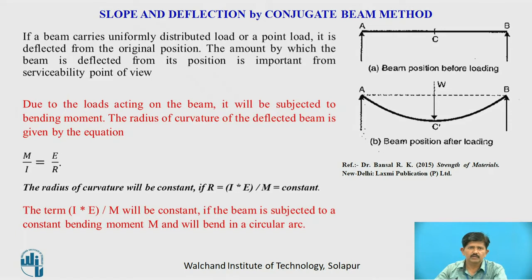So, there is much more importance to calculate the slope and deflection of the beam. If a beam carries a uniformly distributed load or a point load, it is deflected from the original position. The amount by which the beam is deflected from its position is very important from the serviceability point of view.